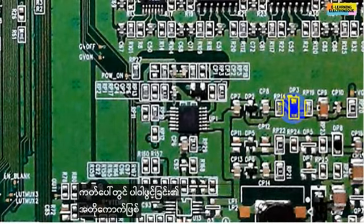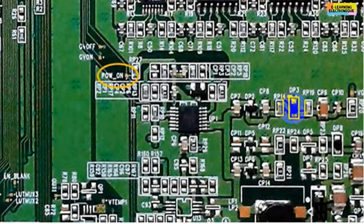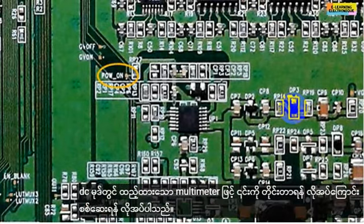In the following example, the power-on signal coming from the microprocessor is written on the card under the label POW, which is the abbreviation of power-on. To check if this voltage comes out of the microprocessor, it is necessary to measure it with a multimeter put in DC mode, at the test point just mentioned.